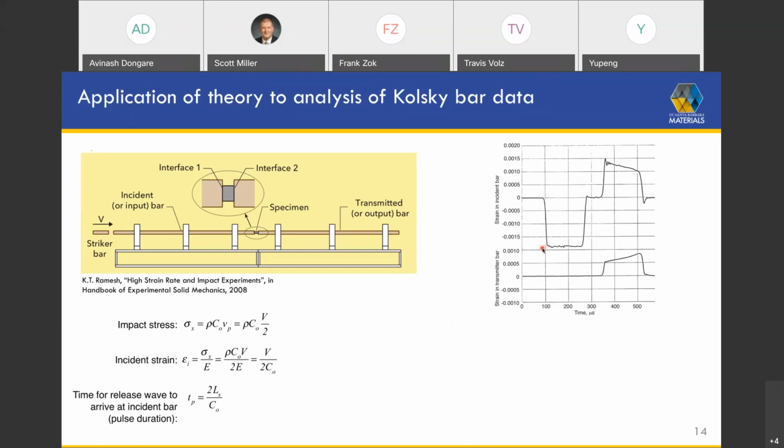Those kinds of materials where the lattice resistance is important, and recognizing that the lattice itself represents a short range type of obstacle, those obstacles can indeed be overcome through the addition of thermal energy. And so those materials you'll find exhibit a stronger temperature sensitivity as well as a stronger rate sensitivity. If you look at the mechanics of those mechanisms, you find that the strain rate sensitivity and temperature sensitivity go hand in hand. Now, taking this out to even higher strain rates, what you find is you get into domains